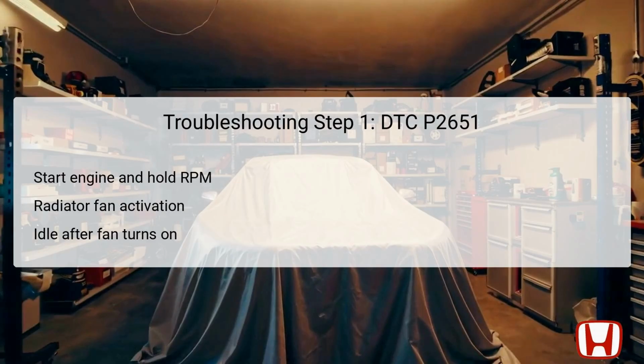Once you've confirmed that the radiator fan turns on, you can reduce the engine speed and let it idle. This procedure sets the stage for subsequent tests, as it ensures the vehicle is operating under conditions where the PCM can effectively assess VTEC functionality.